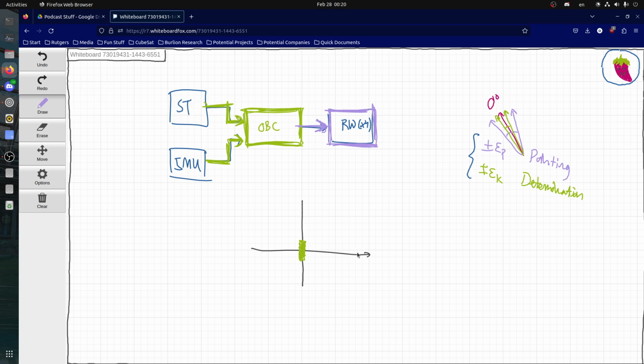Usually, the largest signal will be right in front of it, and then there'll be little bulges sticking out the sides. That depends on the gain of our antenna. It depends on a ton of antenna features, which Shri will mention when we have the communications podcast. This one bulge is the main lobe, and this is what you would want to point at a ground station.